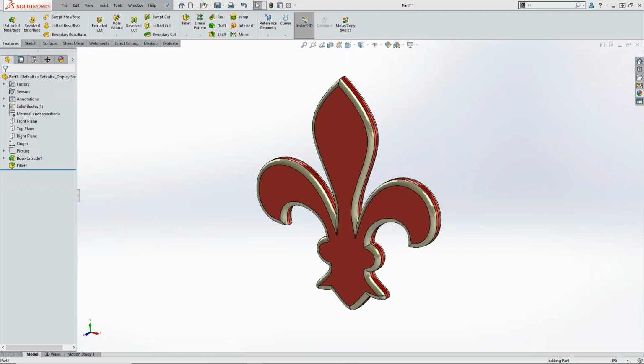Yeah, this is Rob. Can you just use fully defined sketch to complete your spline? You can, and in many cases, that's going to give you sometimes all of it, sometimes some of the dimensions, but it gives you a start. Fully defined sketch is a nice tool. It doesn't work as efficiently or as thoroughly on splines, but it is a pretty good tool. Really nice shortcut for other images that you have to import. Good question.